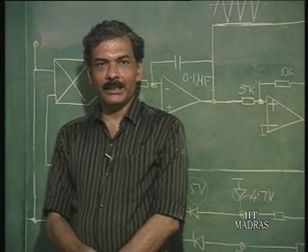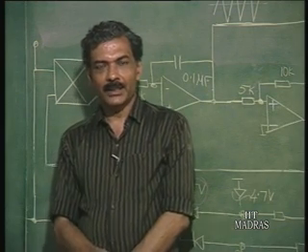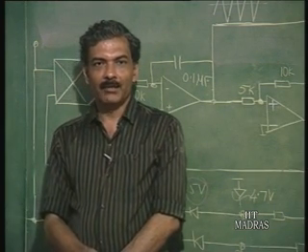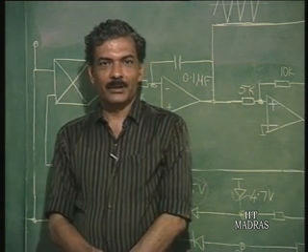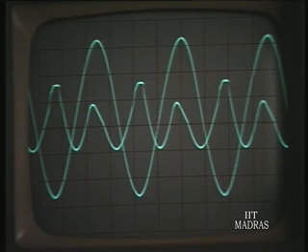Now, without the modulation, you can see the output of the multiplier when the phase lock loop input as well as the AM input both are given to the multiplier. Okay. You get omega_c into omega_c, that is twice omega_c, sin omega_c t into sin omega_c t, sin squared omega_c t, which will contain a 2 omega_c component there. So, there is no modulation now. Okay. Now, she will apply the modulation, just apply the modulation.